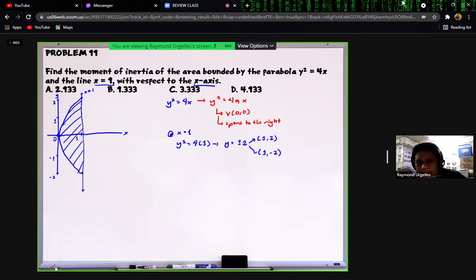No? Pag ang hinahanap natin is with respect sa x-axis or sa y-axis, ang pinakamagandang gamitin is rectangular strip na parallel dun sa hinahanapan natin na axis. For example, dito x-axis is horizontal, so therefore we better use the horizontal strips. Okay? So yung reason, diba, is pag horizontal strip, pag kinonsider natin lahat ng points sa horizontal strip natin, equidistant lang siya from the x-axis. So lahat sila equal sa y-coordinate. Diba? So nung parabola natin. Okay, so pare-pareho sila ng y-coordinate so with the point on the parabola. Okay? So kaya yan yung pinakamagandang gamitin, horizontal strip.